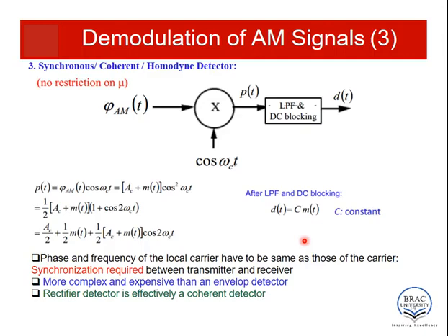Another key point: whenever you build a modulator circuit, you may need a bandpass filter of omega c frequency, and for a demodulator, you may need a low pass filter of omega c cutoff. Even though its operation is very simple, implementing the circuit is very complex, as you have a multiplier here. But the previous circuits simply required only diodes and capacitors.